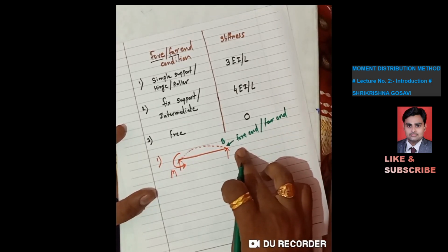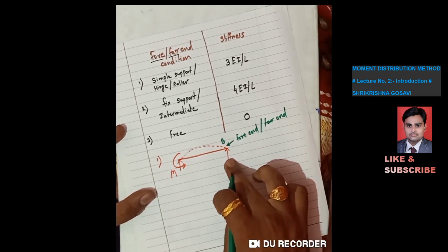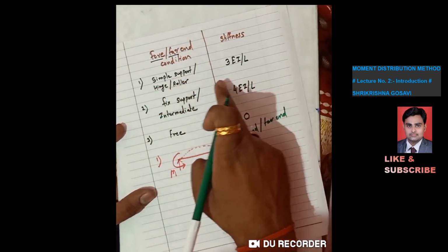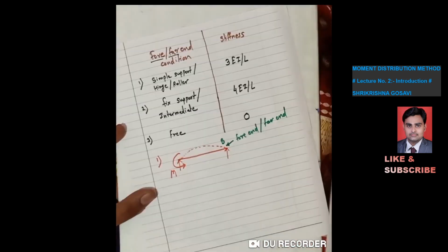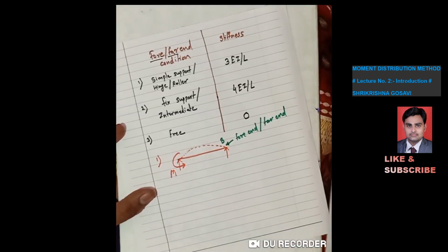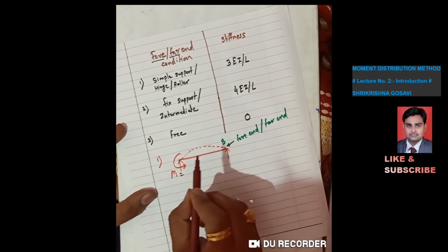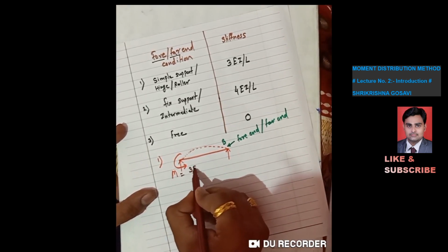Now this far end is what? It is here a simple support. So in case of simple support, if the far end is simple support, then the stiffness is 3EI by L. So I can write over here M is equal to 3EI by L.